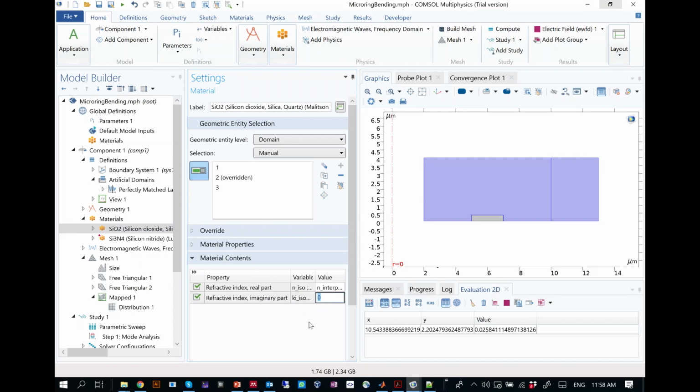If you have one material that absorbs and one that doesn't, because one is a high quality oxide and the other a low quality oxide with some hydrogen in it that absorbs in the telecom wavelength band, you can manually change the values of this absorption to model that. Then as your mode changes, because the overlap with the different materials changes, this would also be factored into the absorption you get as a function of frequency. But that is something in practice that we never do.